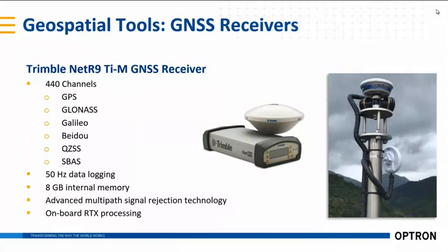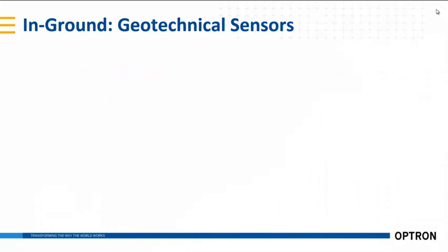Often your total station position and the reference station, the reference prisms, are located quite close to the edge of the pit or within a zone of influence from the mining activity. And utilizing a GNSS receiver in tandem to the prism monitoring solution can give you an excellent overview on how your control points are behaving and whether they're stable or not.